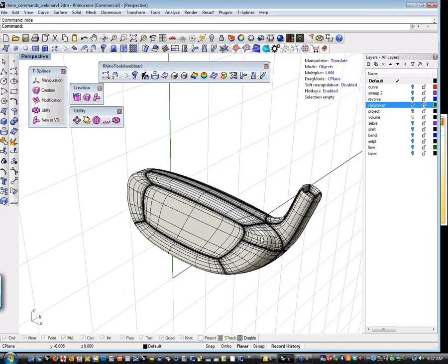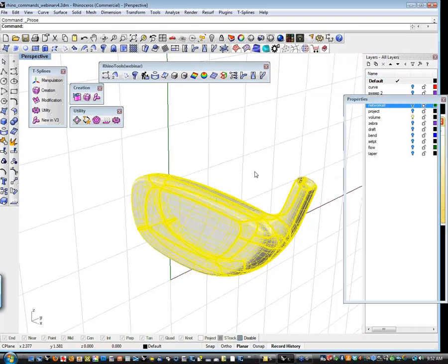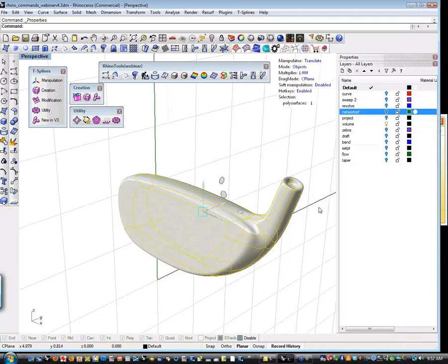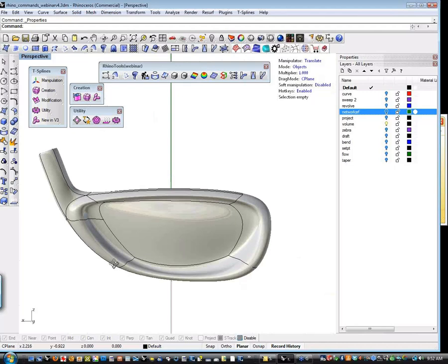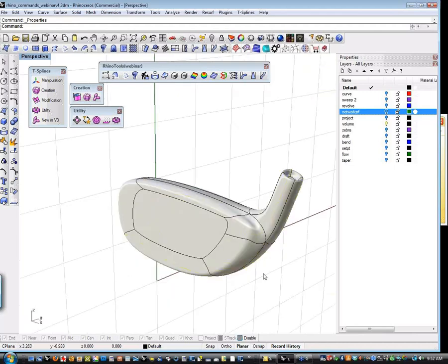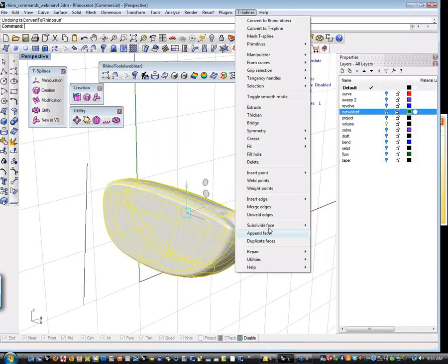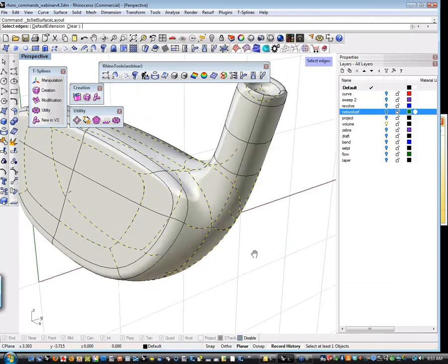Yeah, so there are a few different controls for how you can specify this to be split up, but if you are using something like Rhino Gold that's setting gems on specific surfaces, you will want to be aware of the NURBS patch layout inside T-Splines. So if you want to undo and go back to T-Splines, Kyle, and then go in the T-Splines drop-down menu and click on, let's see, I think it's probably Utilities. Yeah, Define Regions for Conversion. This will show you how the T-Spline is going to be broken up.